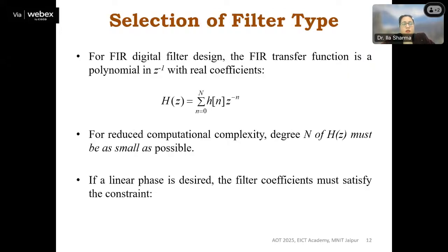So for digital FIR filter, in today's lecture I will consider the designing of FIR filter for simplicity, because in FIR we need to realize only zeros, or a smaller number of coefficients as compared to IIR. So I will be discussing this FIR digital filter more.